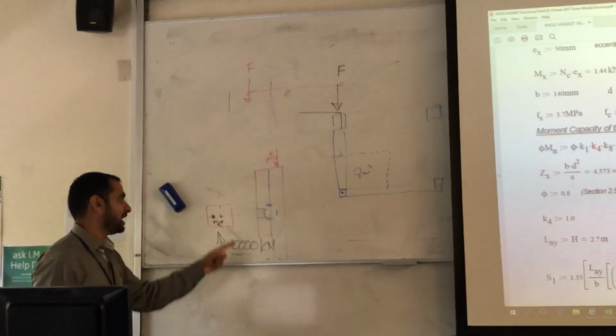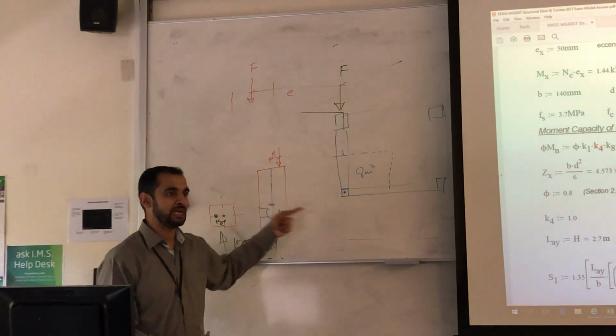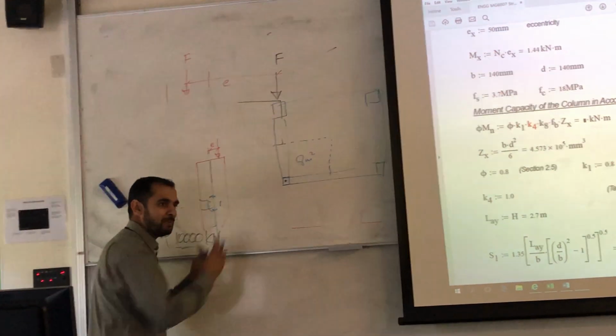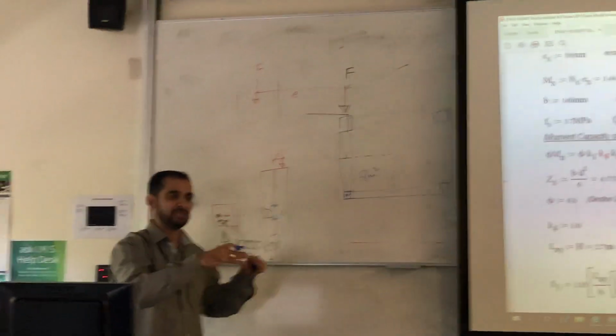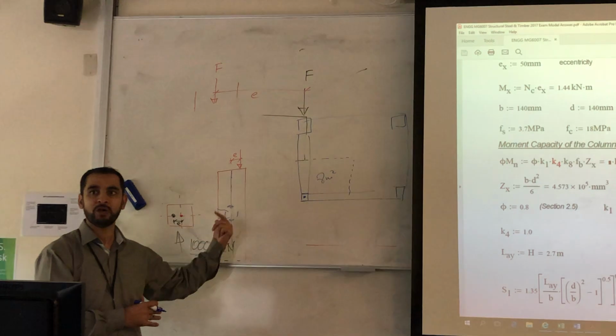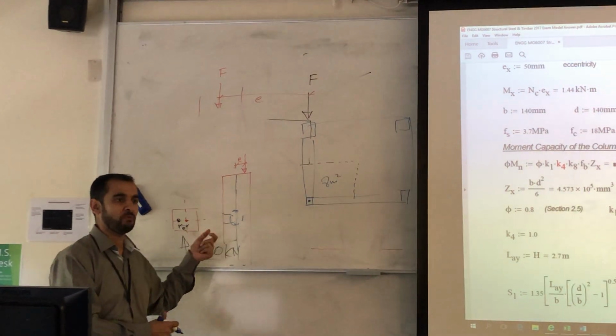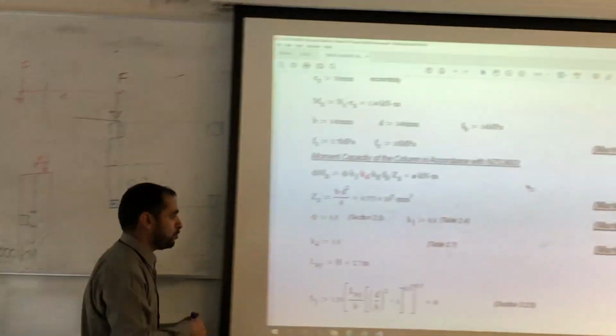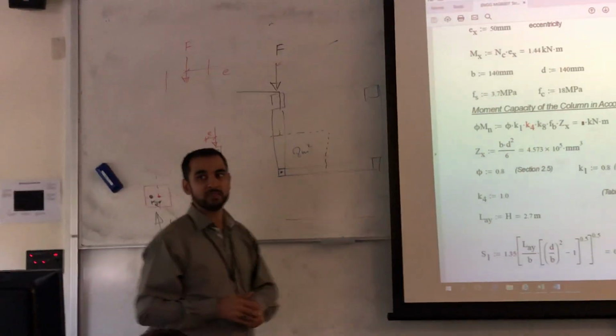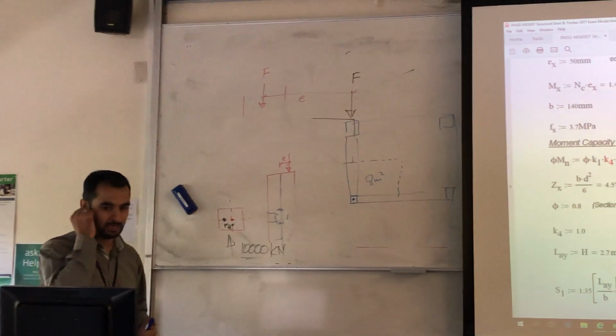If it's one member, and there is a knot, that could be going through the entire section. While if we have more than one member, these defects are distributed. If they're staggered, they're not at one location. So you have one member stronger, even if there's a defect in the other one. So that's why we take that into account. That's the purpose of doing this.